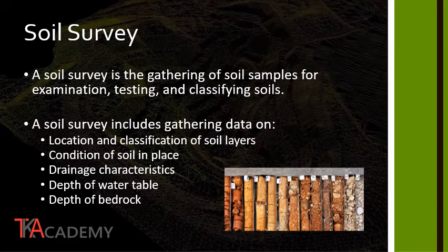On any design and construction project, it is critical to know what the soil characteristics and properties are before commencing work. A soil survey must be conducted as one of the first steps. A soil survey is the gathering of soil samples for examination, testing, and classifying soils. A soil survey includes gathering data on location and classification of soil layers or profiles, the conditions of the soils that are in place, drainage characteristics, depth of the water table, and depth to bedrock.